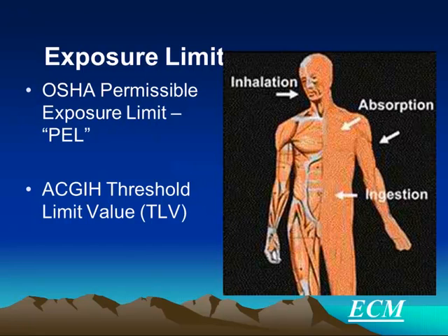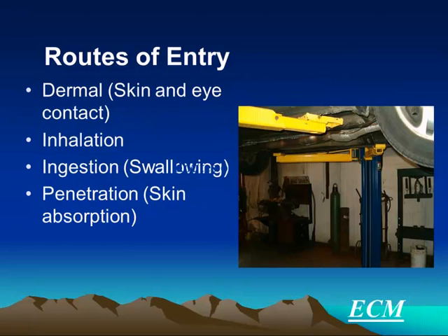You can have hypersensitivity. So if you're doing a job in the dealership and you're noticing some symptoms, dizziness, headaches, whatever, that's where you want to pull out the MSDS sheet and take a look at that. And depending on what you're doing, you could modify your practices. So say there's better ventilation, have a fan nearby, or use an alternate product, whatever. So that's where you shouldn't be over the PEL, but again, you might want to be aware if you're noticing side effects when you're doing a task with chemicals.